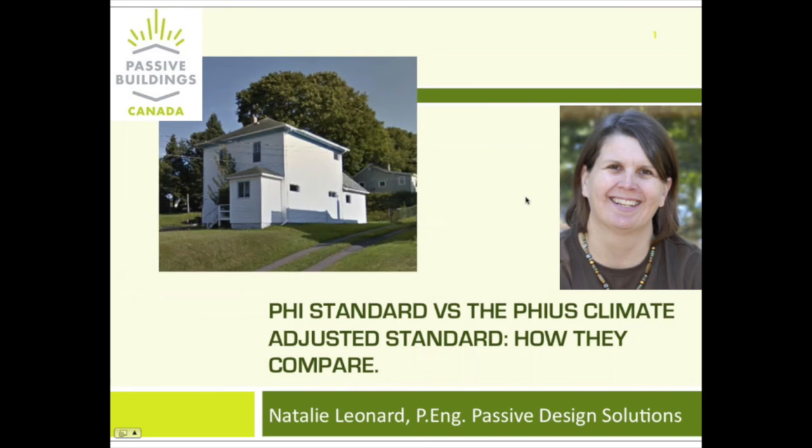So PHIUS kind of separated that out and made an adjusted sensible recovery, and also collected the watts per CFM or CFM per watts. Can't remember which order the units go in, which are the two numbers you need for energy modeling in both PHPP and WUFI Passive. So that sheet's available. It's publicly published on PHIUS's website under their resources.